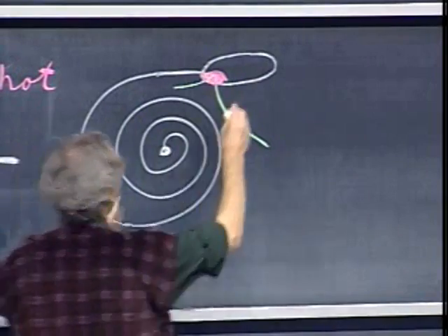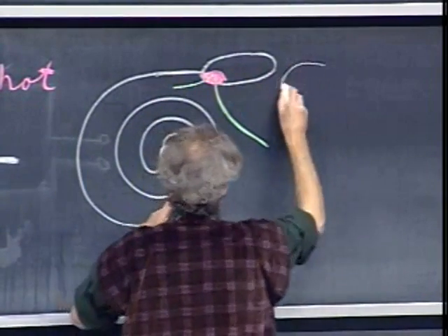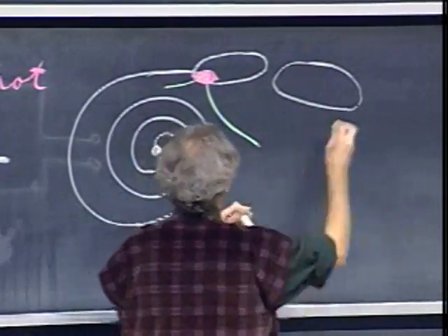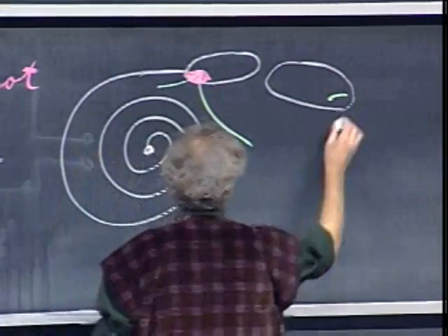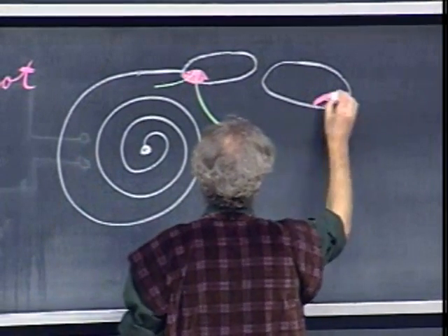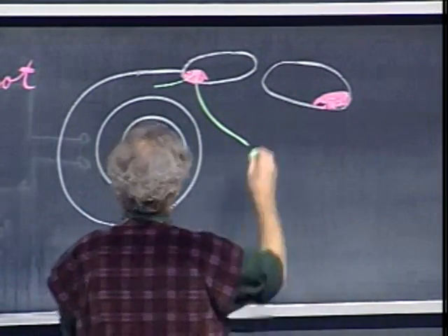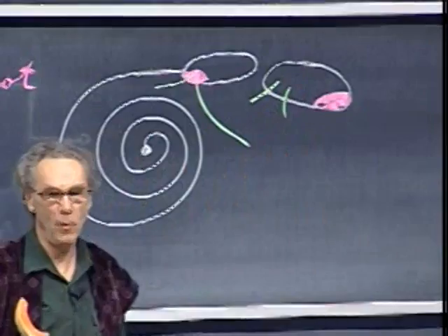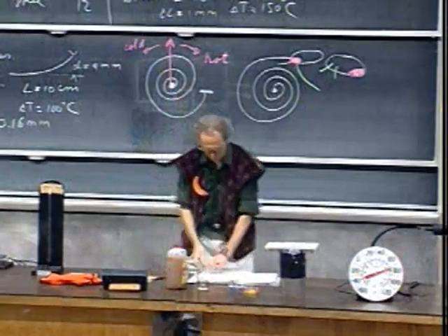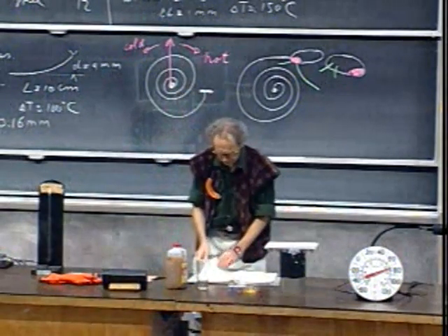And so there comes a time that this glass thing will go like this, and the mercury rolls out. And when the mercury rolls out, these contacts here are open, and the heater will stop. And that's in almost every room. Very genius device.